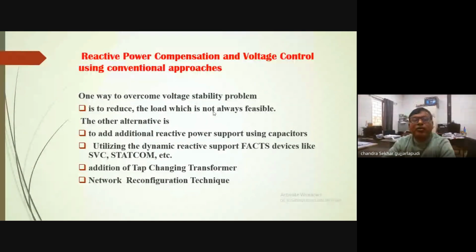In a power network there may be a number of series switches as well as some parallel ones. That means sectional switches are there as well as some tie switches on the distribution side. By operating those switches, the overall structure of a network can be changed.